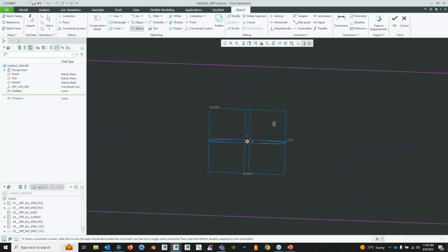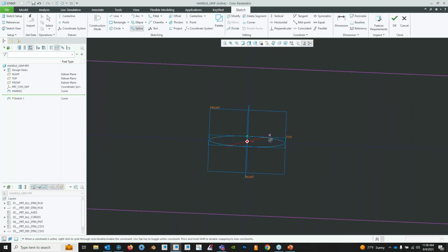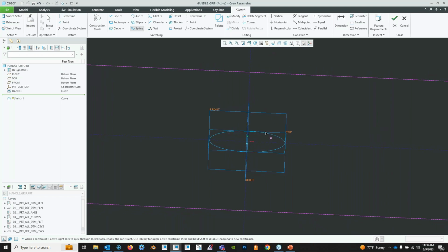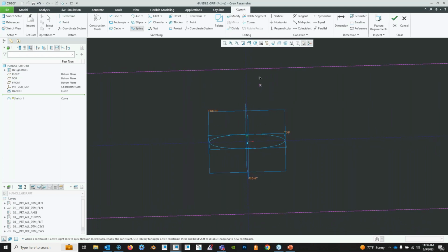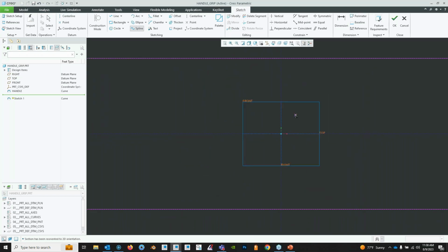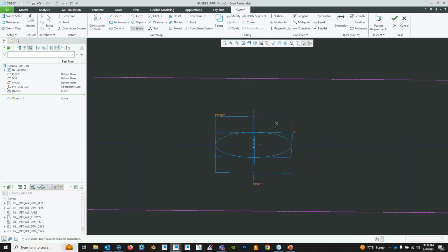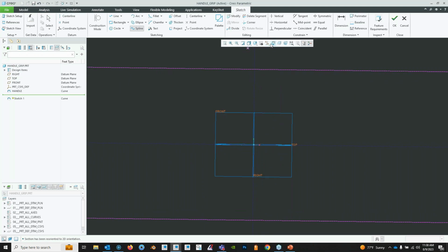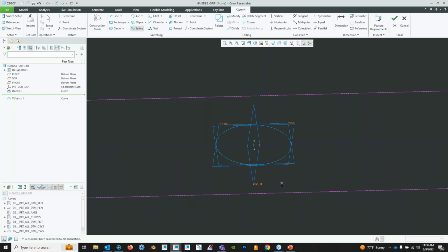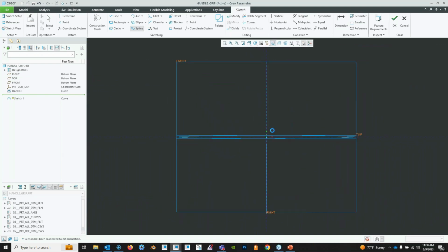Right now, all I want to do is stay within this ellipse right here. This will be the handle when it's extruded. And then I'm going to have 2 separate sketches going down here that will be splines that will eventually be merged together. So let's say I want to make the finger grip part, and I have 2 center lines to give me my distance here, because I want it as an entire distance of 10. Like I said, it's remaining parametric already. And I'm just going to sketch out the finger grips here.